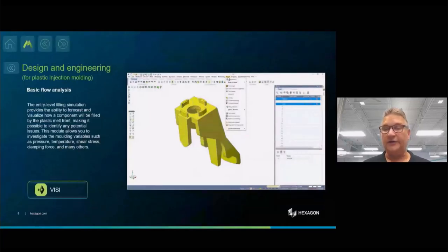All these are important factors and can be analyzed at the beginning of the process with just a simple model, as you can see on the screen, without editing anything else. In this example, you can see if the thickness of the part is reasonable to have ideal cycle times, and if the filling with the selected gates is good or not. You can immediately start to avoid issues with this tool.